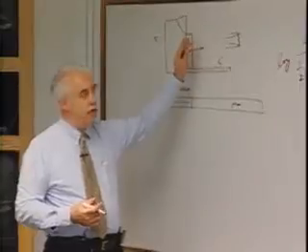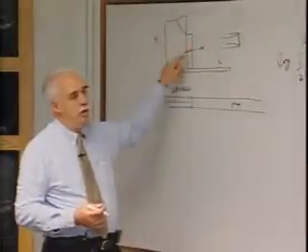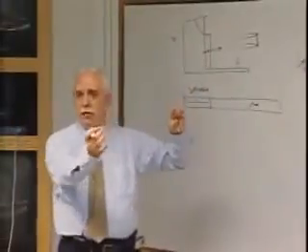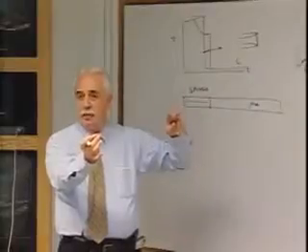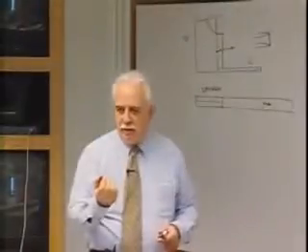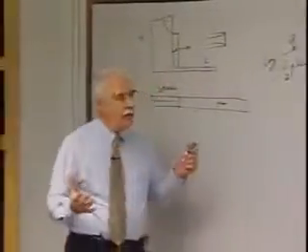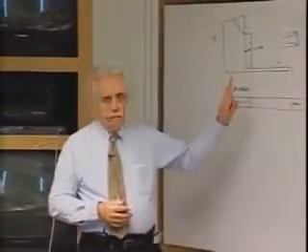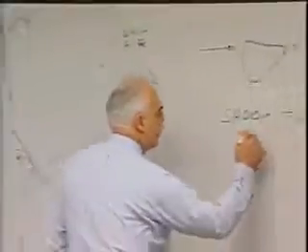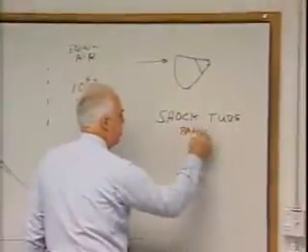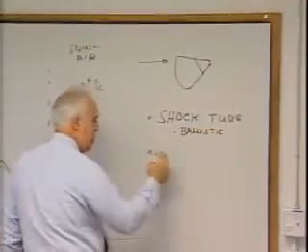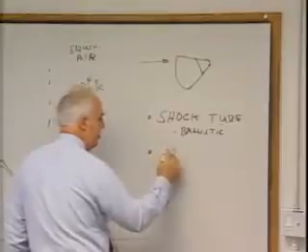Getting to these energy levels is extremely difficult. There are three facilities you can get to them. One is a shock tube. Second is a ballistic facility where you fire a projectile that looks like what you're going to fly. And that does a good simulation job, except it's very small, and getting any measurements is very difficult. If you go into a wind tunnel, you can get great measurements, but you can't get the energy. So the shock tube and ballistic facility have the difficulty of measuring things.